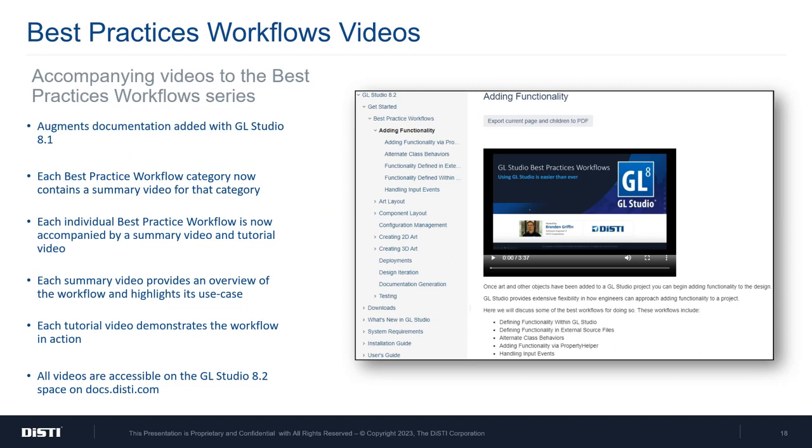So each high-level workflow category now contains a summary video for that category. Each individual workflow within a category is now accompanied by a summary video, which provides an overview of the workflow, and a tutorial video, which demonstrates the workflow in action. These videos are all accessible on the GlStudio 8.2 space on docs.disti.com, which I will now show you how to navigate to.